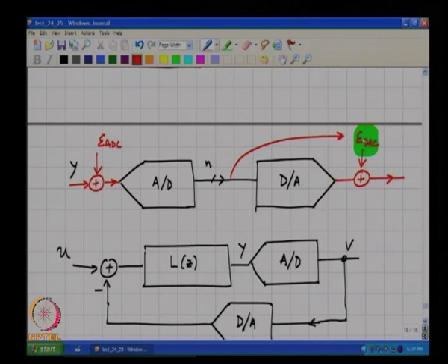Okay. So, now let us see what the effect of these errors. Please mind you, these are all deterministic errors, there is nothing random about this. Once you make a DAC, you can actually go and find the errors in the threshold of the output levels of the DAC. You can also find the errors in the thresholds of the ADC, right.